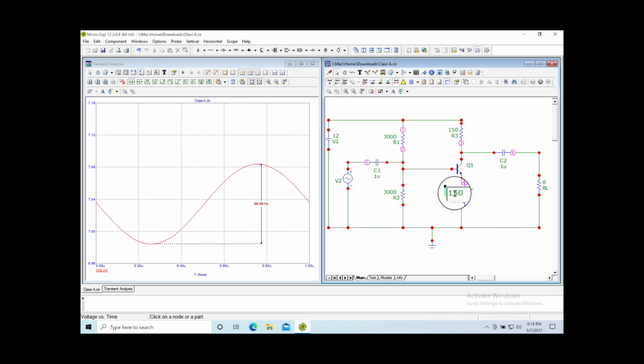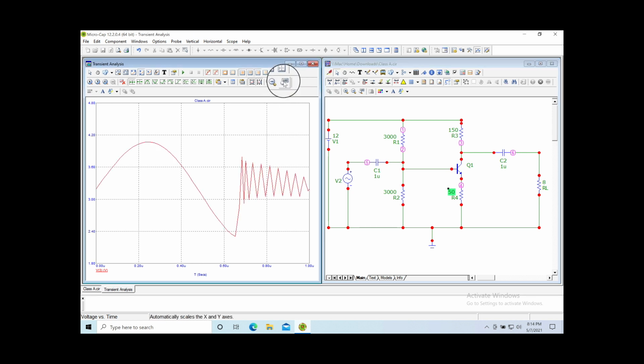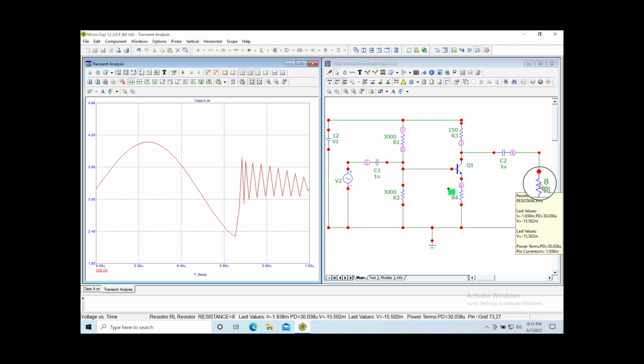Let's click on this. I'm going to make it 50 ohms. That'll make it easy. Just backspace. Whoops. Got to auto resize our window again. Whoa. Okay. Now look, two things. One is we're not up around 6 volts anymore. We're down around 3. And as this signal goes low, something happens. It just goes crazy. And I think the problem is this signal tries to go low, there's not a lot of current left to come down here. And this guy, our 8 ohm resistor, is just, I think, kind of shorting this out.